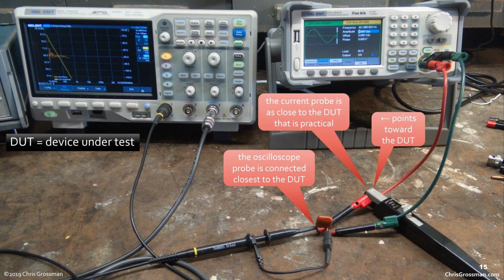But if you keep a nice neat layout like this, don't cross anything over here, keep this short, this is going to be under the picofarad, probably in the hundreds of femtofarads, but not in an area that's going to bother us. If you move this probe up, the capacitance is going to increase.